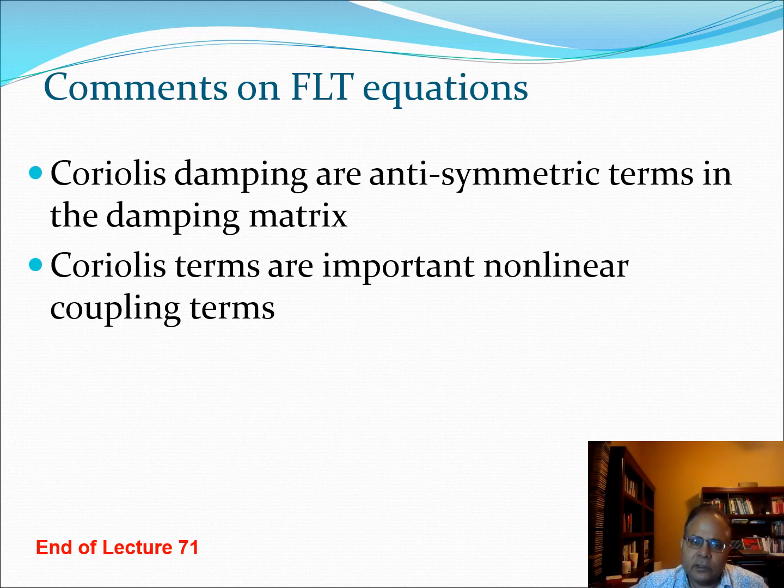So that was the video about the Flap-Lag-Torsion system, and you clearly saw that all the terms derived previously were incorporated in this system, and what was new is essentially some Coriolis type of terms which came in because of the coupling. And these coupling terms are important because many times when helicopter dynamics was coming up as a discipline, there was a great lack of correlation between predictions coming out of these models and actual experimental data or flight test data.